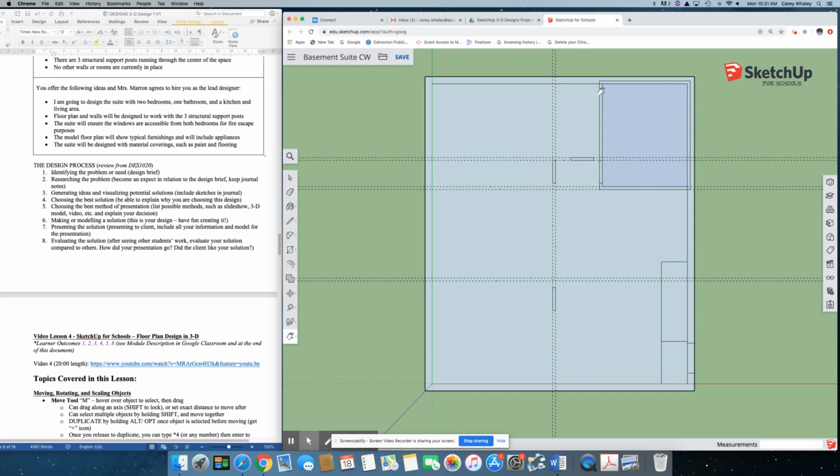We do have this wall in place for the utility room, but I do need to create these walls over here. You can do that a couple different ways. You can do like what we did here, draw one rectangle, then do the offset to build out that wall space, or you could use your line tool. For example, with a line tool, you could click on this line, go over here, and over to that space there. That might be faster, so I'll go pause and fill in all of those walls.